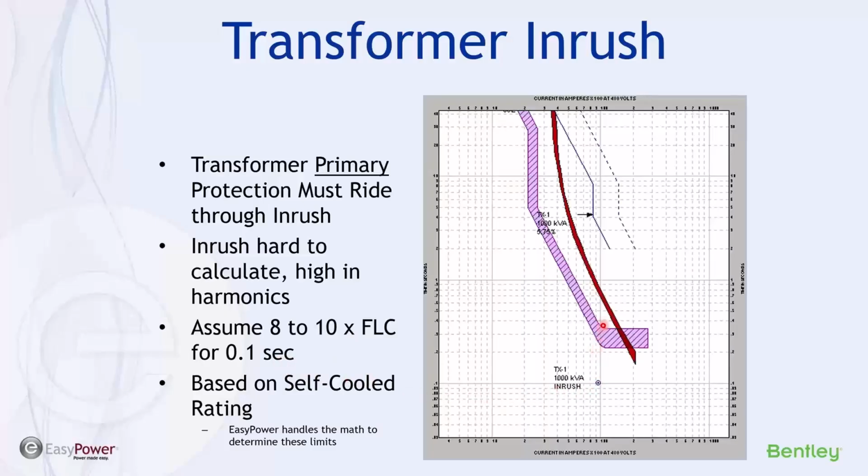And we see that neither of these devices, presumably on the primary side, will be affected by the inrush. And most of the problem is that the inrush current is very much harmonic, it includes harmonic currents, and it's difficult to know their response on a protective device.